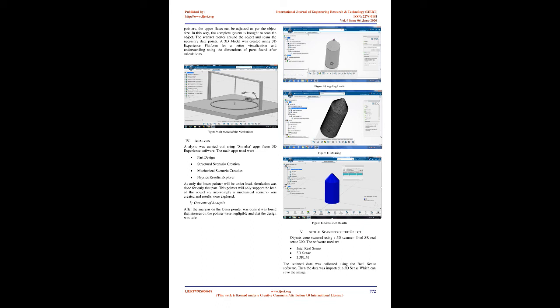Model: the platform rotates on the rail with the help of a wheel. The wheel is connected to the motor. After giving power supply to the motor, the wheel rotates from the inner side of the rail. The outer side of the rail is supported by two bearings, which are exactly opposite to the wheel placement. A belt runs over these two bearings and in this way the stand rotates smoothly.